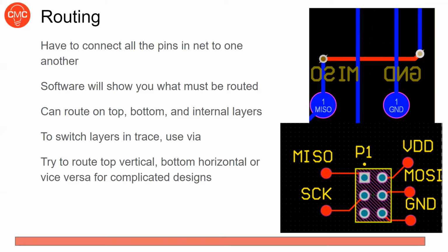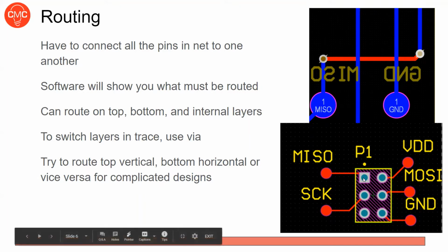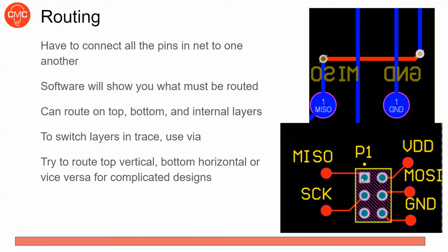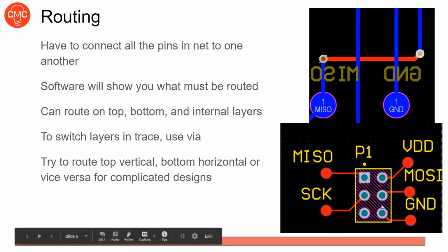You really want to minimize the amount of vias that a trace goes through to maintain signal integrity. It's okay to use them, and again, for all these layers and components we have here, it's really low frequency signals, so it's not really a big deal. But just to get some good practice, try to minimize the amount you're viaing through. Okay, and these are all the pins, and these are test points, and you can just route to all the test points.